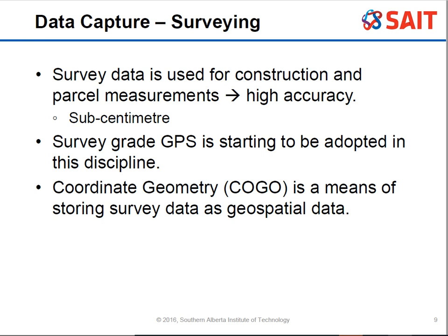And GPS has been around for a while. But survey grade GPS is because if you need a high accuracy GPS, you can definitely use it to create control points. It's expensive, and again, make sure you know what you're doing with that, and I would suggest doing a geomatics program if you're going to use a survey grade GPS, so that you know what errors are expected and what it means when you are working with that data.